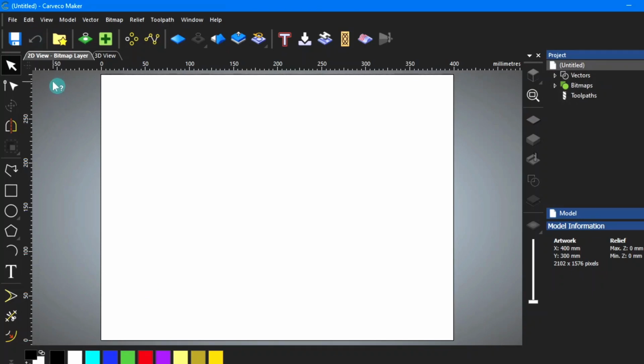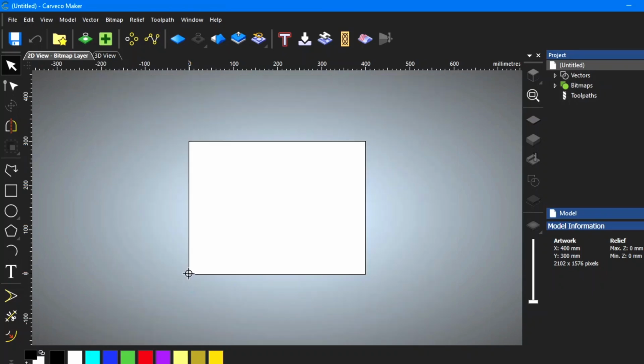Okay, so it indicates it here. See, it's 50mm negative, so it's passed this way to the left of that line, and everything to the right of that line is a positive number. And same goes in the Y direction down here. Notice this is a negative number away from the material. Everything is a positive number away from our starting point.